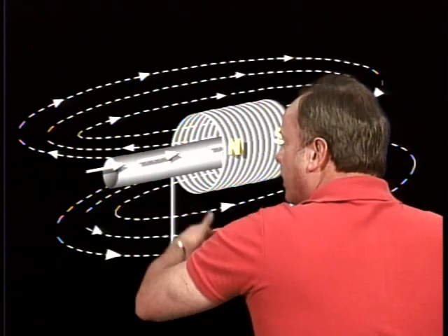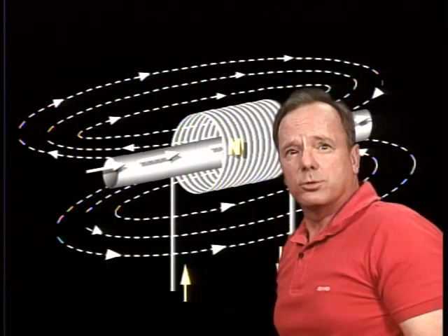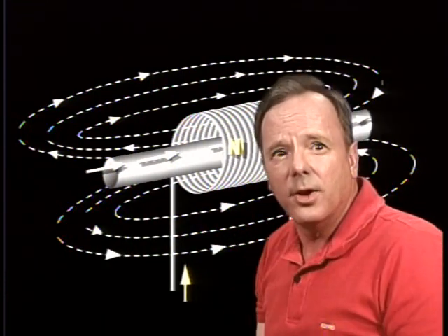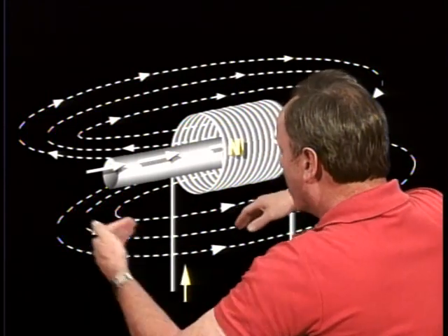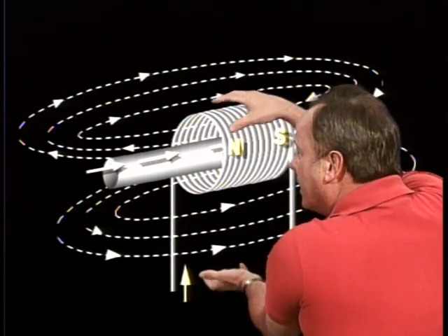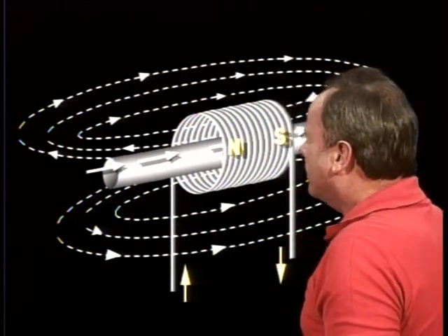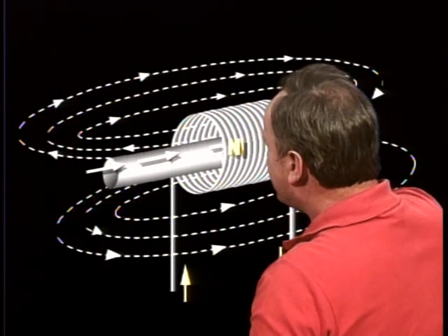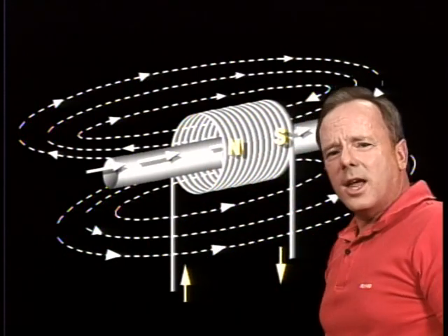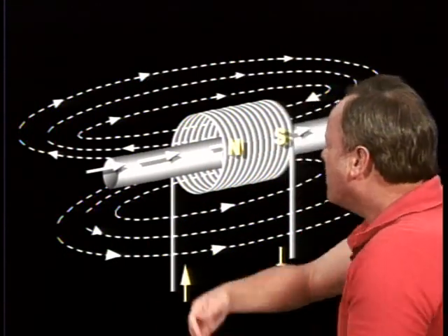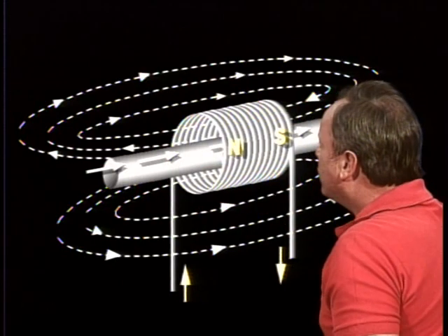And in fact, one of the things you want to know is magnetic lines of force pass most readily through iron when compared, we'll say, with copper or aluminum, and therefore putting an iron core in here really concentrates the magnetic field. Now, another bit of information you might want to know is that if you took an electromagnet, let's assume you don't have any current through this wire right now, and you just take any kind of magnet for that matter, take a magnet and wave it by this wire.